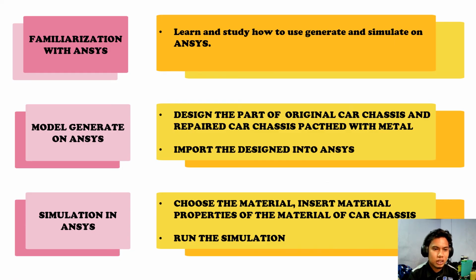Familiarization with ANSYS. Learn and study how to generate models and simulate in ANSYS. Model generation in ANSYS. Design the parts of the original car chassis and the repaired car chassis patched with metal. Import the design into ANSYS. And lastly, simulation in ANSYS. Choose the material. Insert the material properties of the car chassis material and run the simulation.